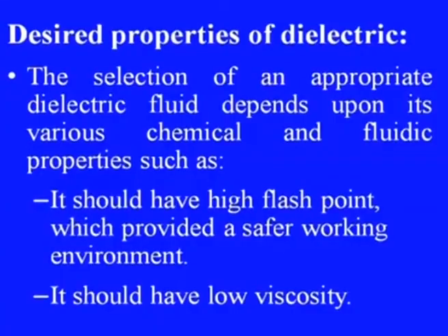Then this dielectric is also responsible for flushing away the debris that is produced in the cutting zone, and of course, it cools the workpiece and electrodes, otherwise they will continuously get heated and the appropriate dimensions of the workpiece will not be achieved. Now, let us briefly see what the desired properties of a dielectric are.